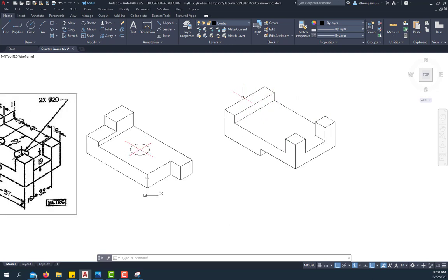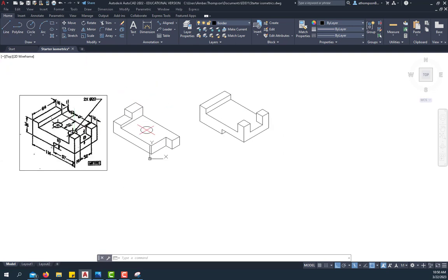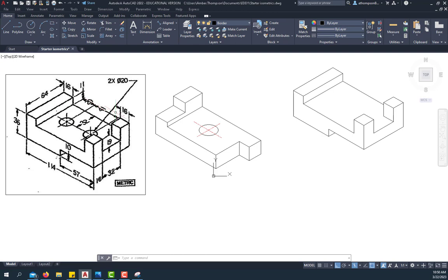The circles are going to be the same way. We have to make lines to find the location. So this is 20 from this line here, then another 41 and 32 across. So we're just going to make a line over top of the lines, starting in that end point. We'll go down 20. And just to keep our spot, we can go in 32 right here because we need that point. And then we can start back in the line command and go down 41, enter, and then come over 32 as well.